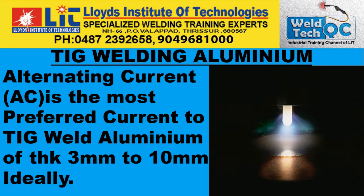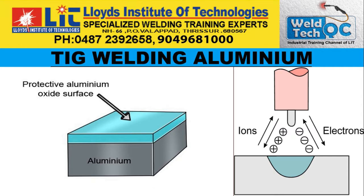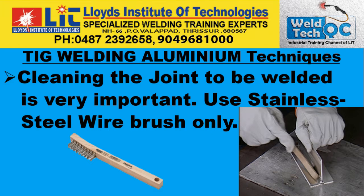Alternating current is preferred by many for TIG welding of aluminum because it provides an efficient balance between penetration and cleaning action. The cleaning action is required because there will be an oxide layer on the aluminum base metal, and this needs to be removed just before the welding starts.